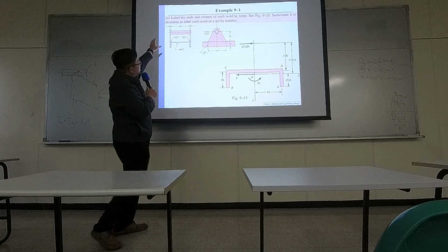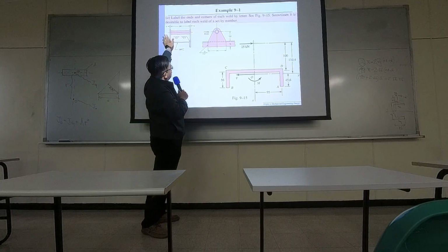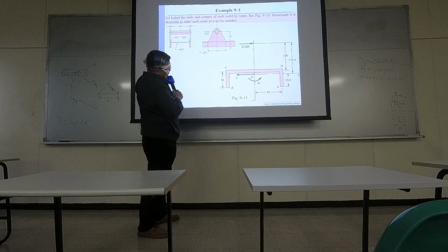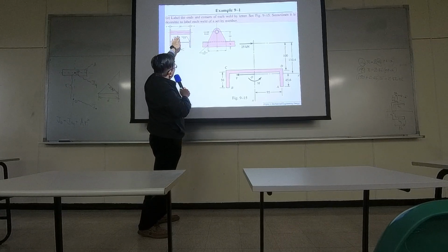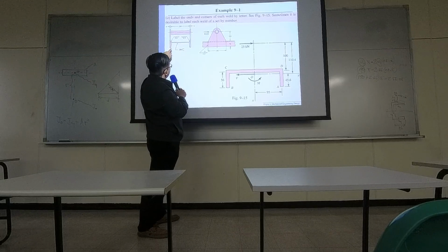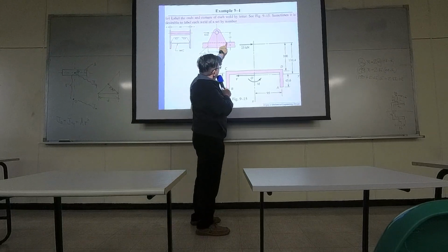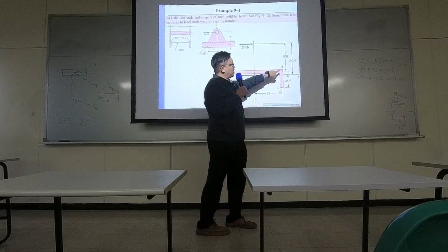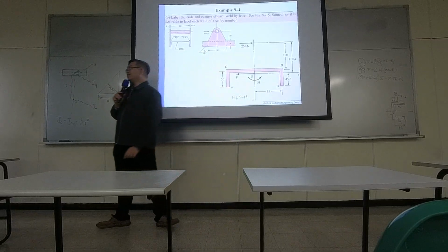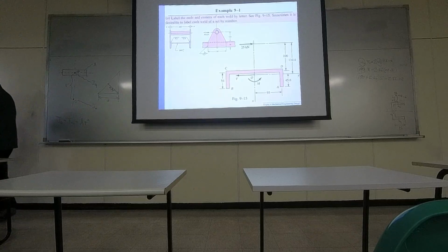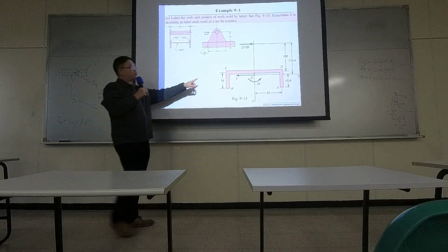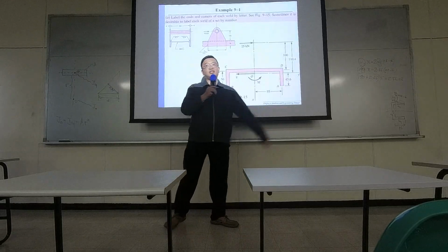So in this case, you have a horizontal bar, and you have a force applied onto the bar, and you have this C-shaped welding here, and in the end, the weakest points will be C and D because they are carrying the most shearing stress. So if it's going to break, it breaks from C and D.